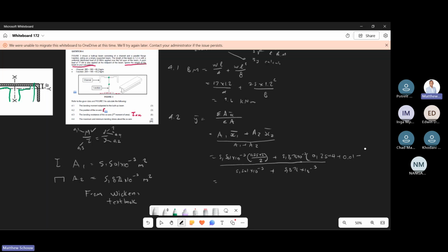You know the one that you're using, I think that's a taper channel. I see. Anyway, I'm just gonna go with that one. Fine. That's 27 now, so it's gonna be minus 0.027. We all understand how I got that value. So we're coming up all the way till the end of that thing. We're adding the height of the I-beam, the thickness, and then we're going down, minusing that AY to each respective center of the channel over there.